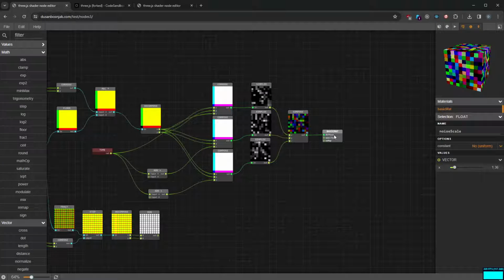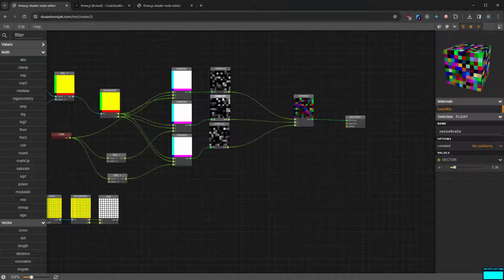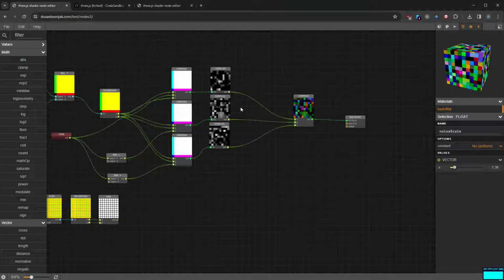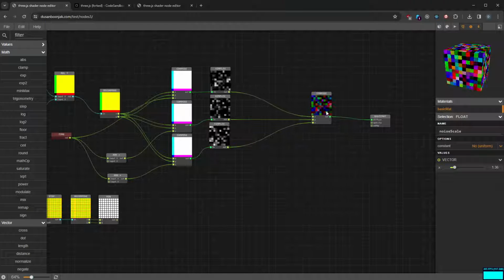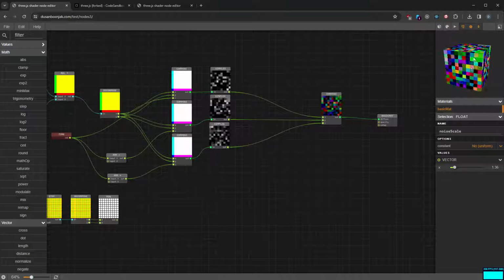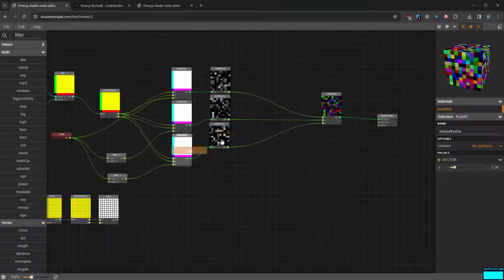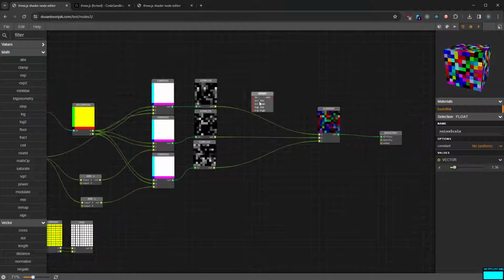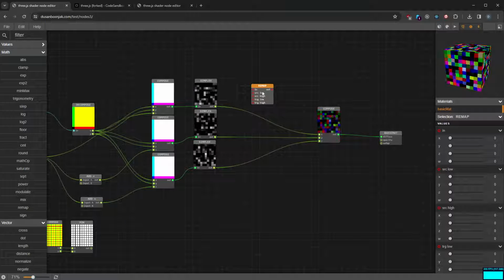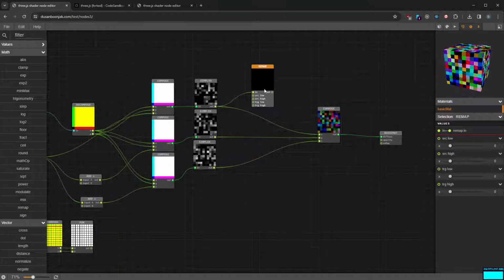There is an issue with the noise function. It also has a negative value, and it may even be going from 0.5 to -5. But for now, let's get rid of the black values here, because they're going below 0. There's a remap node for that. All three of them will need the same configuration. So in goes the noise.